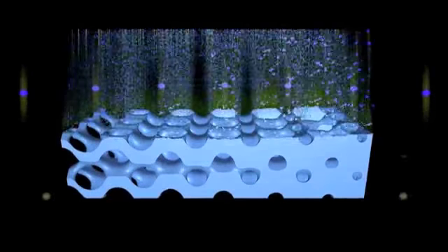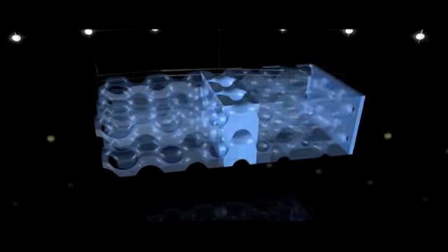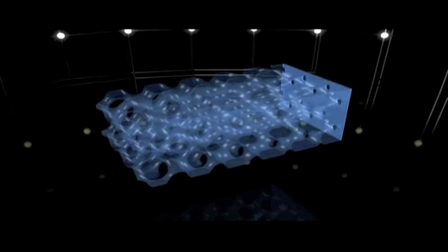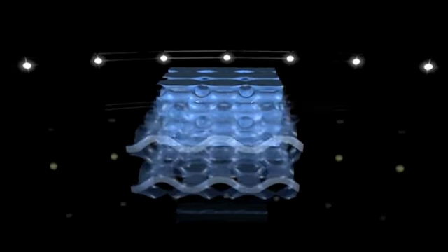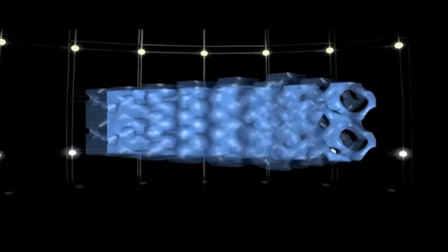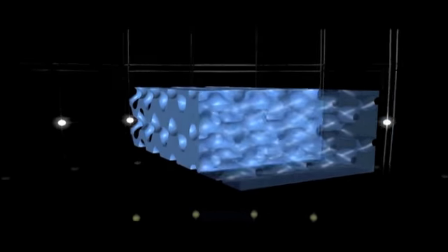Here is an animation we've created of the same kind of 3D printing process, but this time of a much more complex design. This is what we call a lattice structure. It's a structure that cannot be made using any other manufacturing technique. It has double angles, it has very long aspect ratios, and it's something that cannot be made using casting, milling, injection molding, or anything else. You can see this actually almost resembles a material in that in some areas, let's say at the end, it has much more porosity, whereas the other end smoothly gradiates towards a much denser design.